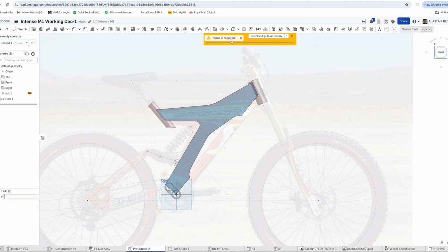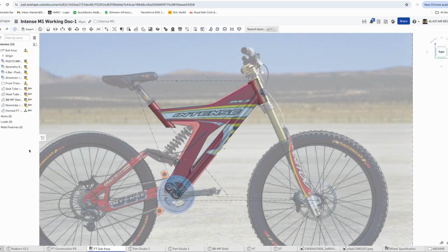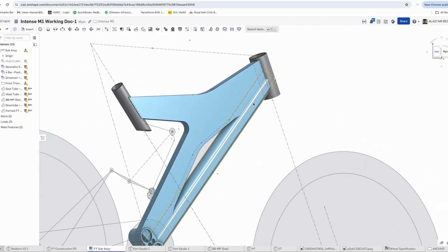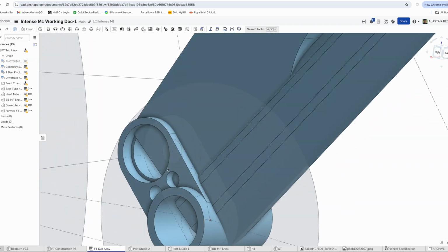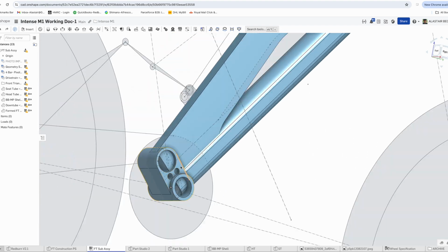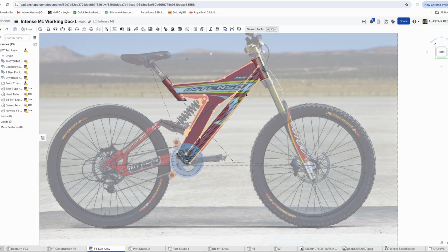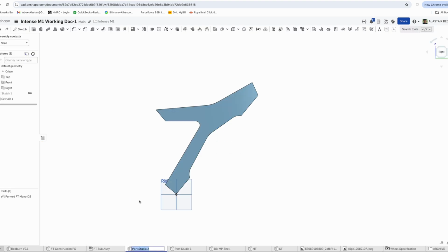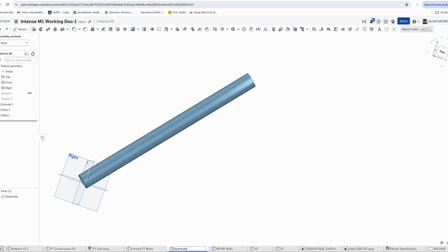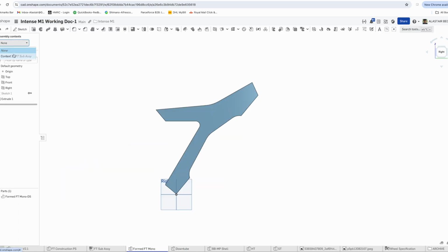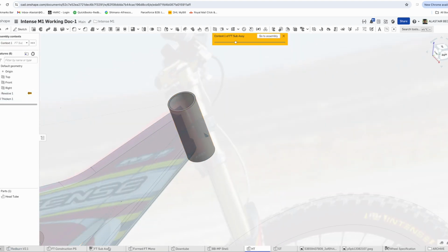But we've extruded out. We've got our solid, and we're going to keep good housekeeping and rename these parts as we go. We're only going to do one side because it's symmetrical and we'll mirror it across. So now we've inserted it and fixed it into our subassembly. Because it's a subassembly, we can check references off the other parts and make sure that everything is dimensioned relative to each other correctly.